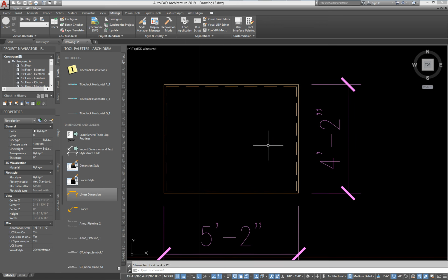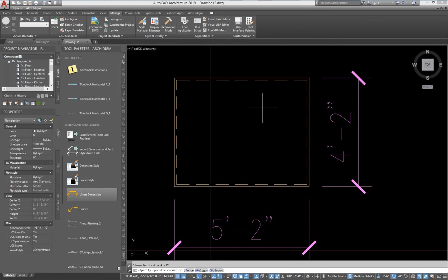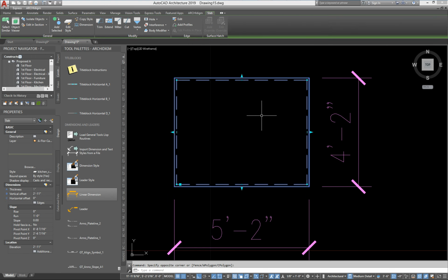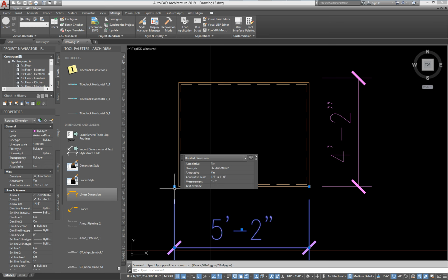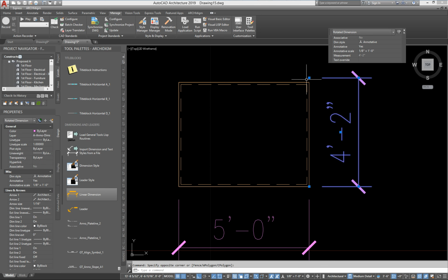Okay, so out to out. If I want those numbers to represent the outside dimension of 5 foot and 4 foot, just make sure what you pull in is the actual edge. So 2 inches here, and then I'll pull this in 2 inches here. And because these dimensions weren't locked to anything, there we go. You can see now. All right.